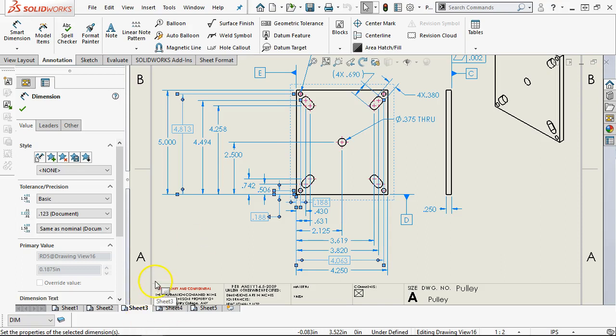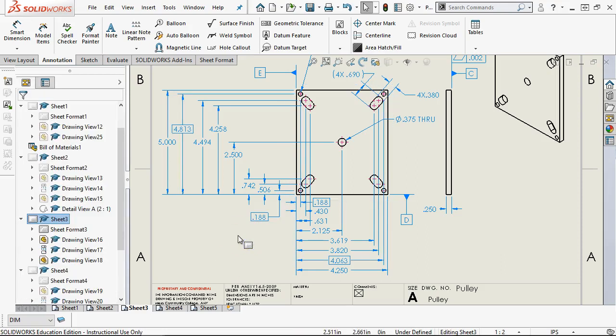The rest of the dimensions at this point, I may build up, and the question is always, if I just put a note down here, all dimensions are assumed to be basic. Well, a basic dimension is usually modified, so you can make the argument both ways: if it's not being modified by something, why do I need to make it a basic dimension? It's not making it exclusive or calling it out as being something that is critical or to pay attention to. All right, so it comes down to practice and going through the process enough to say this is what works.